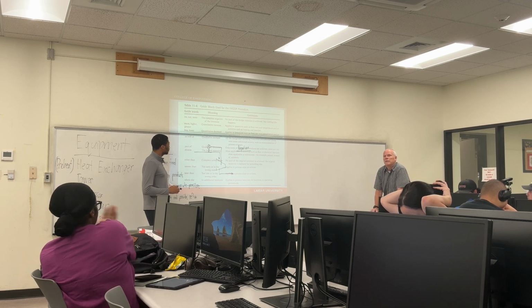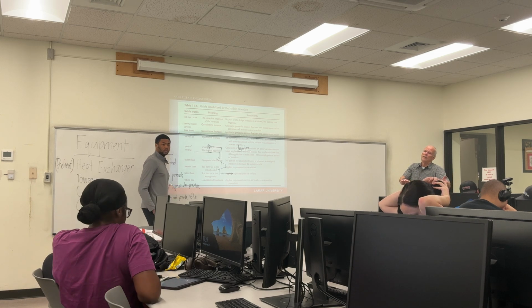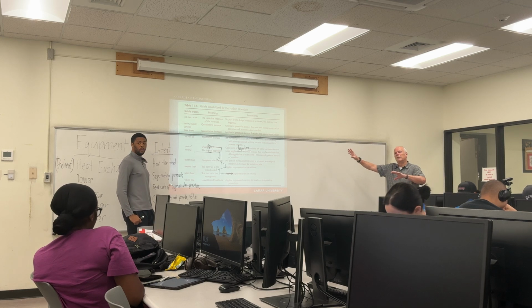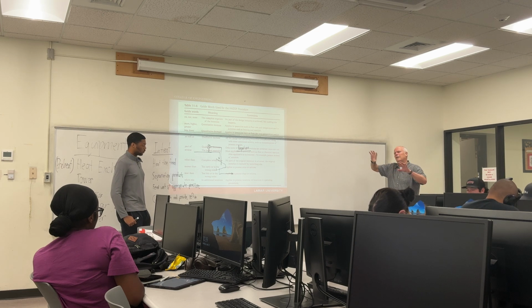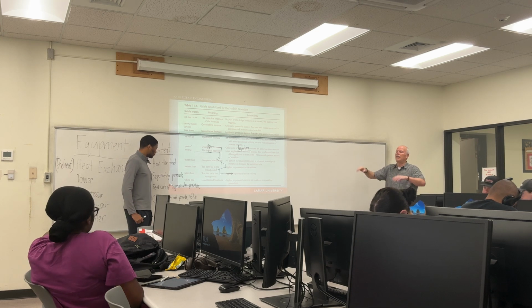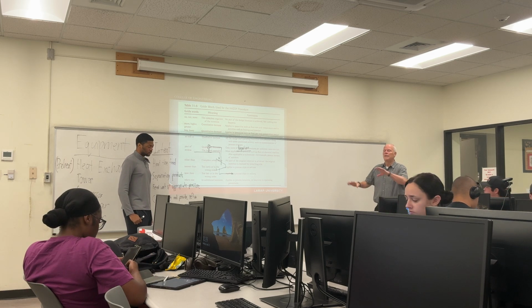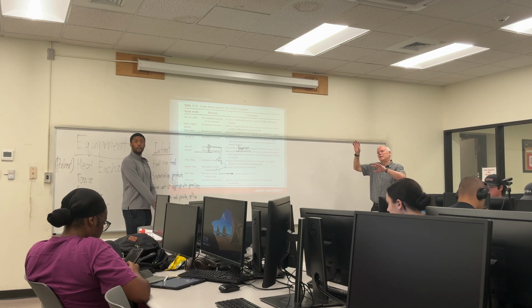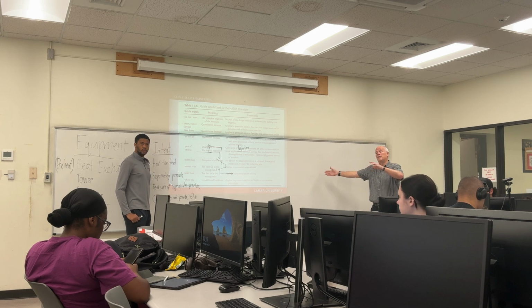Complete negation, right? You're going along fine. Well, what's the pressure of your pipeline? 200. Okay, and then what's the pressure of your unit? For us, it's 300. Only 300? It might be like 350, but it is higher. Okay, so what happens if you're running your unit and you've got this column, this column, this column, this column, pressure goes downhill, right? I mean, it has to, unless you have another compressor to pump it back up again.